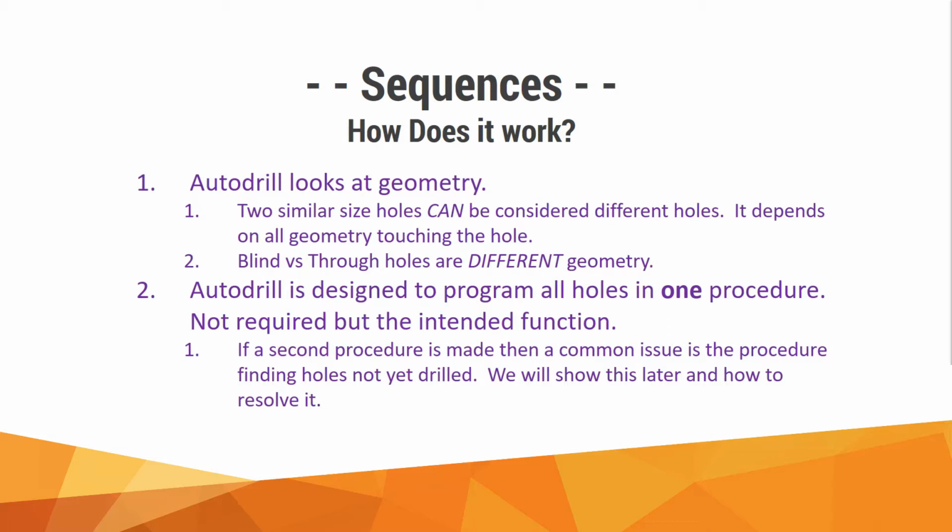Auto drill is designed to program all holes in one procedure. A lot of times in regular drilling, everyone's programming a center drill, and then a drill, and then a tap, and then we have this huge list of procedures, when really, with auto drill, you only need one. So are you required to do it all in one procedure? Absolutely not. But it is the intended function, and you'll see that as we go through the actual part files, how that works.